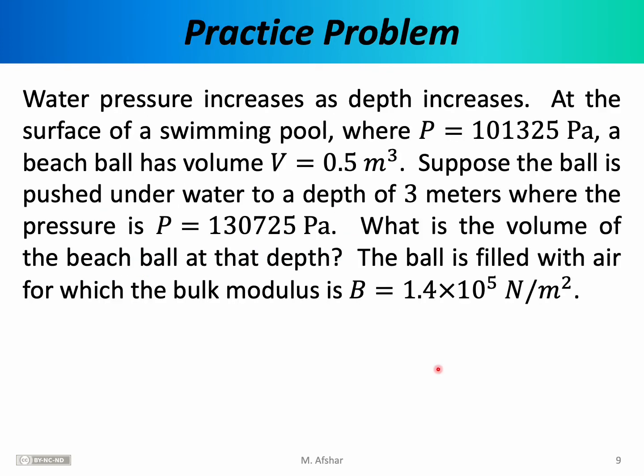Let's do a practice problem involving bulk deformations. Water pressure increases as depth increases. At the surface of a swimming pool where the pressure is 101,325 pascals, that's essentially atmospheric pressure, a beach ball has volume of 0.5 cubic meters. Suppose the ball is pushed underwater to a depth of 3 meters where the pressure is 130,725 pascals. What is the volume of the beach ball at that depth? The ball is filled with air, for which the bulk modulus is 1.4 times 10 to the fifth.